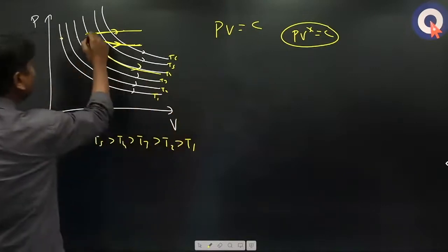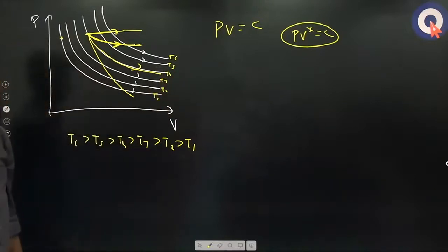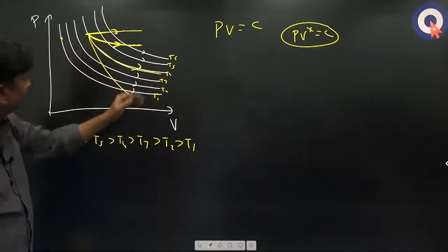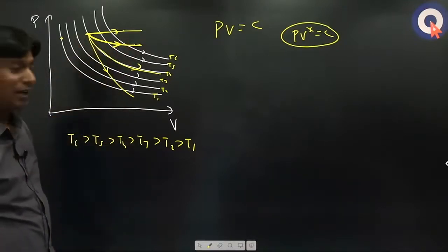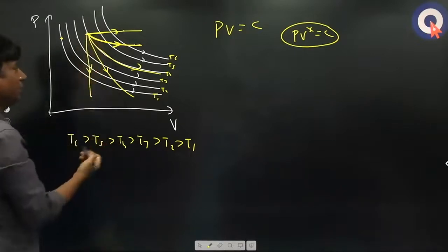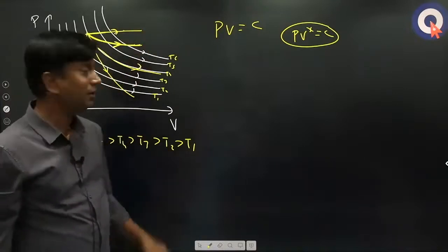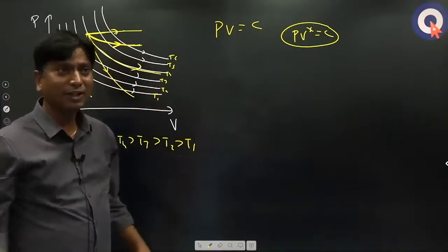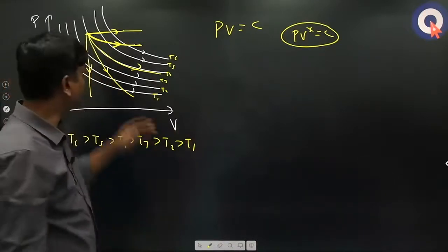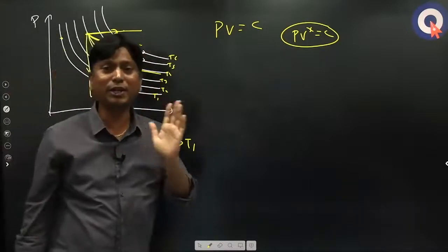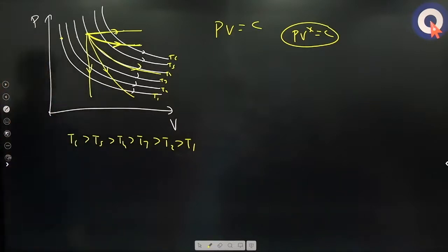And X greater than 1, you will get a steeper curve. Automatically temperature will decrease when the volume is increasing, right? All these are expansions, so temperature will decrease. Even if you are going like this also, temperature will decrease. So in the mind, though the isothermal lines will not be given, by looking at these graphs, the isothermal lines are also there inside. How the curve is going, how the process is taking place, accordingly we can get whether the temperature is increasing or decreasing, right? Okay.